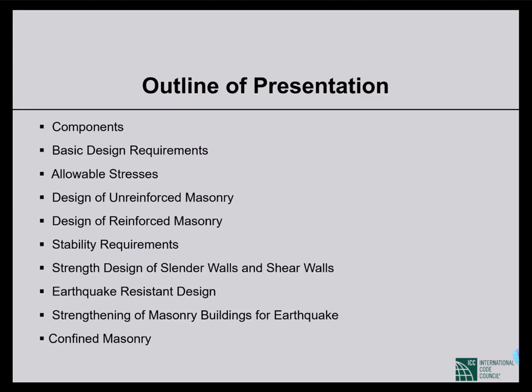How do you evaluate the material strength of an existing structure? Is it possible to do a prism test? This is a very good question. On a load-bearing wall that already exists? Yes, it is possible. In that case, you have to use some jacks to retain the load, number one, for the prism test, if you want to take out a prism from an existing structure.